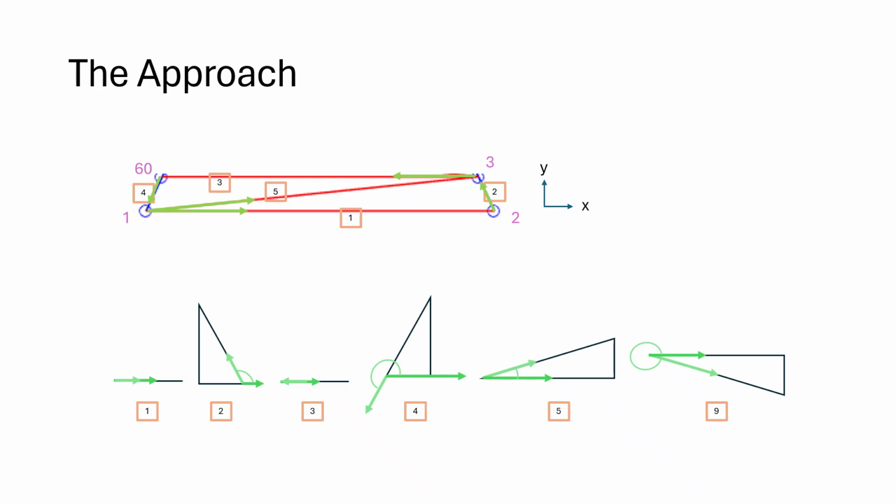My first task, as shown on this slide, was to identify the angle between what we call the local axis of each element and the global axis, which you can see in the middle there is the positive x-axis pointing to the right. And so my task was to create basically an angle between those two vectors for each element. Fortunately, all of them were some version of the six iterations you see on the slide here. So it was fairly easy, once I solved it once, to apply it to the rest of the elements.